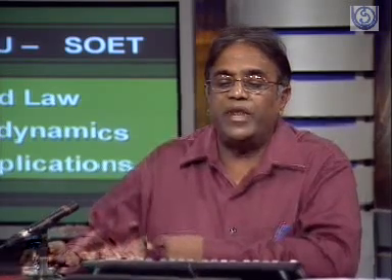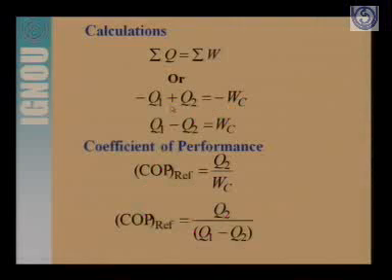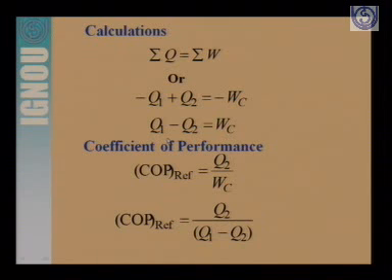Here you see that summation of Q is equal to summation of W, that is minus Q1 plus Q2 is equal to minus WC. So Q1 minus Q2 is equal to WC. In this case we write a very important